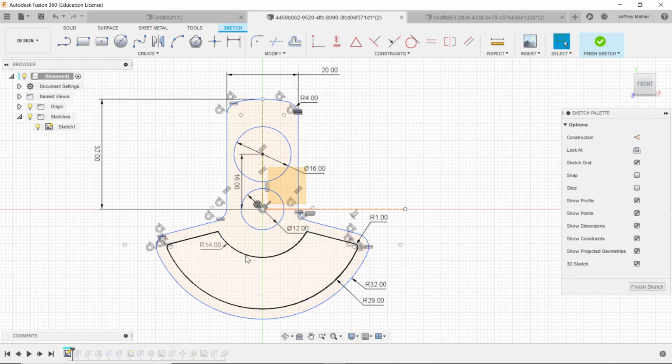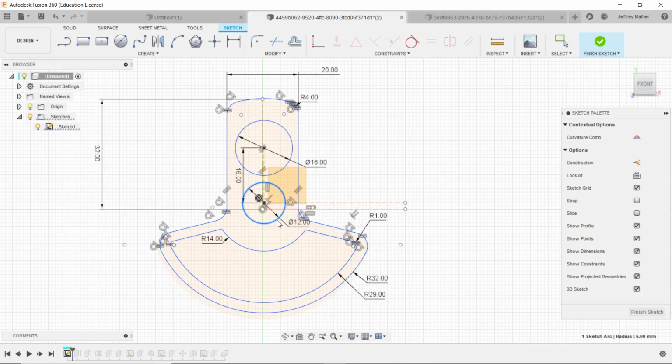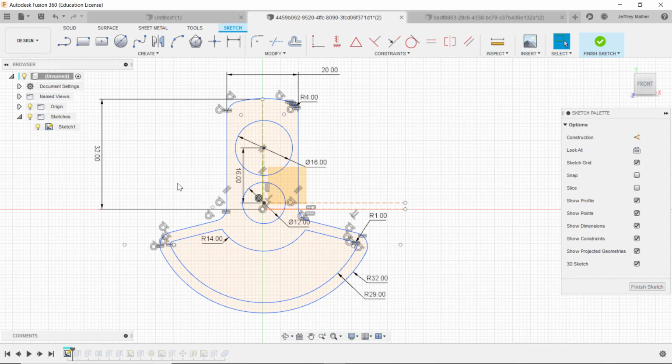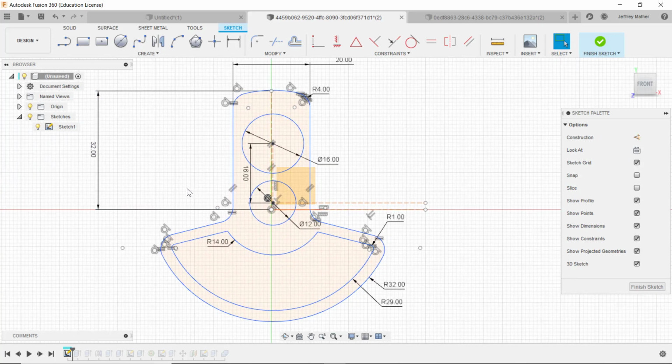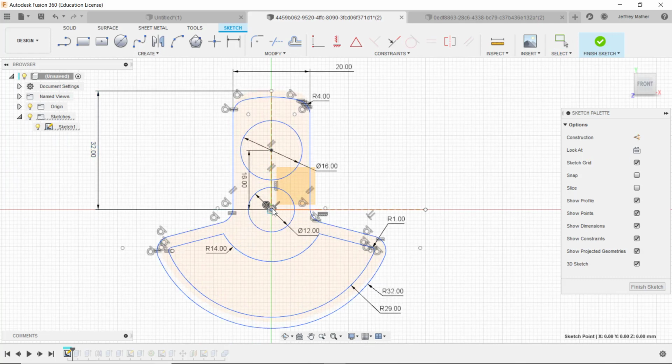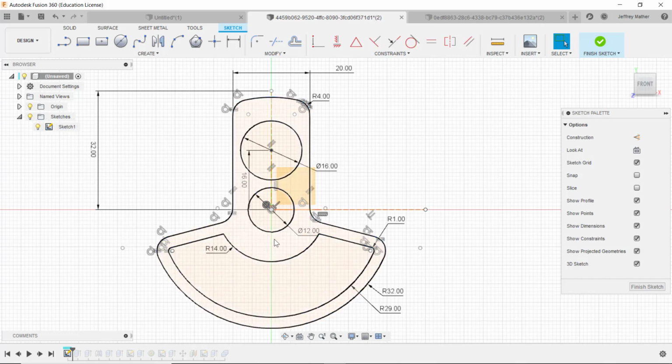Alright, so let's start dragging. This circle looks like the design intent was for it to be at the origin, so let's try dragging that. Whenever something doesn't fully constrain, drag the geometry, and it should be obvious then where you're missing a constraint. So I'm just going to drag this and drop it back there, but I see again that it doesn't fully constrain.